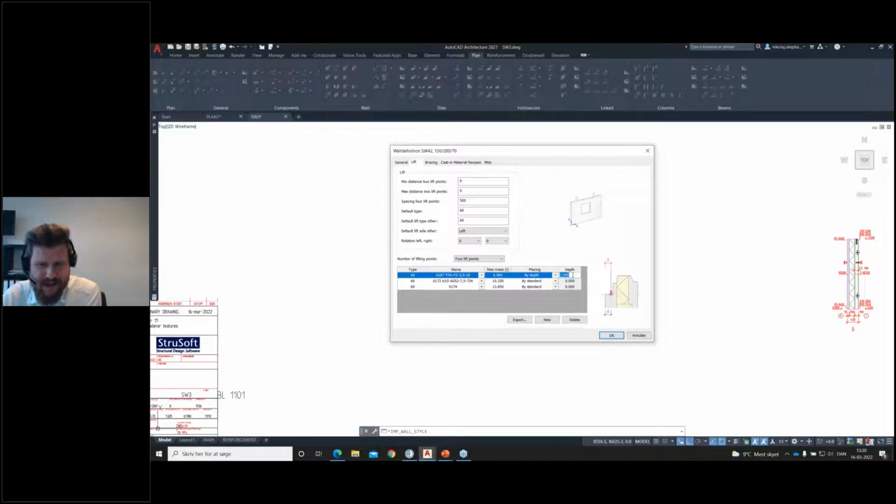But otherwise, with the depth, you can actually have a fixed depth, and it's quite easy to say if you want it in the middle of the back panel here. You have a back panel that's 150, you put in 75 as the depth. So that's the manual depth thing here, but it'll do it in all the elements. It'll still put the lifters in according to the center of gravity on the size of the element itself. It's more like, where do we place it in the section, through the section.